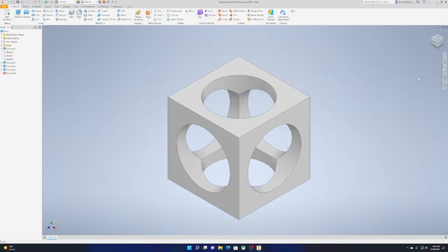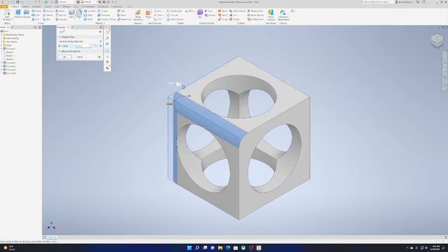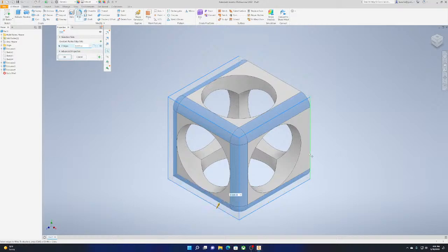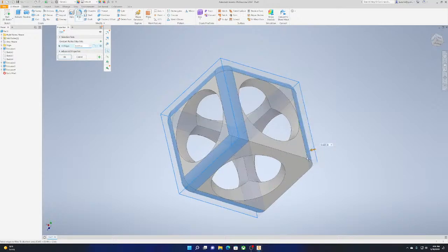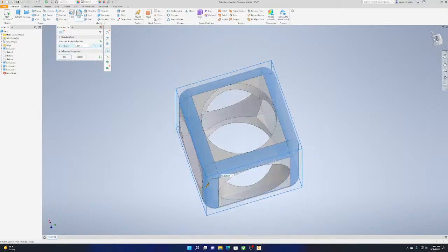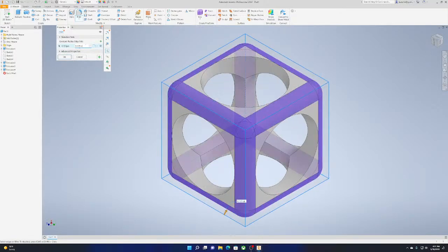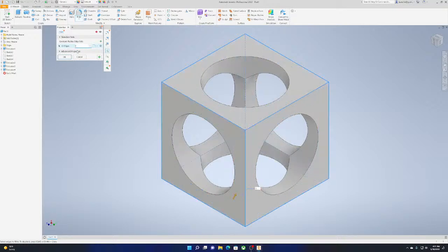So let's make it a little bit fancier, and we can talk about some of the tools that I mentioned. So you can use the Fillet tool, and you can just essentially click on all the edges that you have, and you can see that it shows you this blue preview of what's expected to happen when we do this. You can see I get the whole shape, and I can mess with how much I really want. So maybe I want this, or 5, or if I do like 1, you can see that it just won't let me, I think, because you can't fillet over how much.